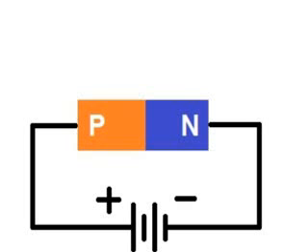When we apply a positive voltage to the p-type end of the diode, this attracts electrons from the N material, and they go diving into the holes in the p-type material like mice into the holes of Swiss cheese. The electrons go diving into these holes and start going through the p region, and now electrons flow from the negative terminal of the battery through the N region to take the place of the electrons that dove into the holes of the p region.